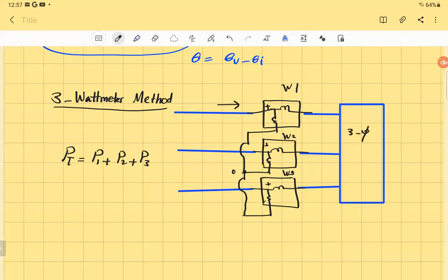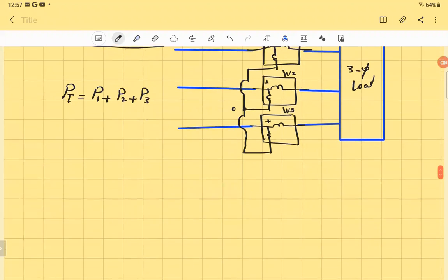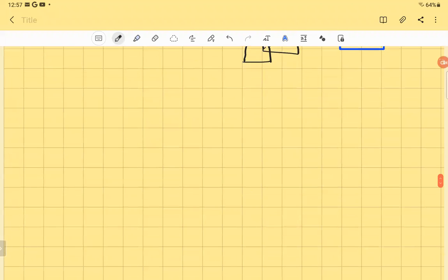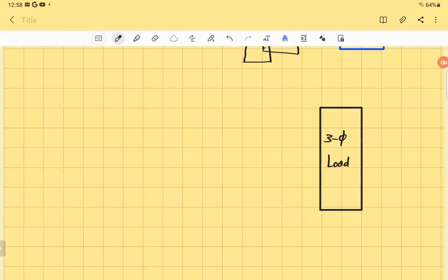And that's the three-phase load. You will do that in the lab. You calculate the power, the Q, the power factor, and the steps will be very clear. And then you will do the same thing using the 2-wattmeter method. They found out that the 2-wattmeter method can be used with just adding simple calculation, and then you save one. So let's just have the three-phase load here. So that's a three-phase load. Doesn't matter delta or star. And we're going to have only 2 wattmeters. Three lines coming here. Supply.